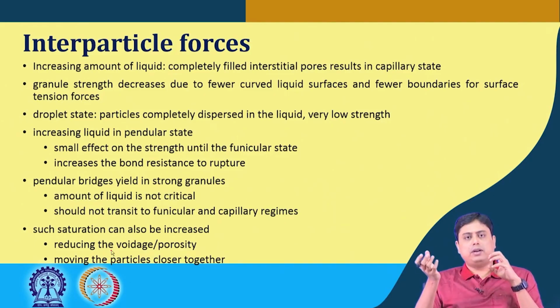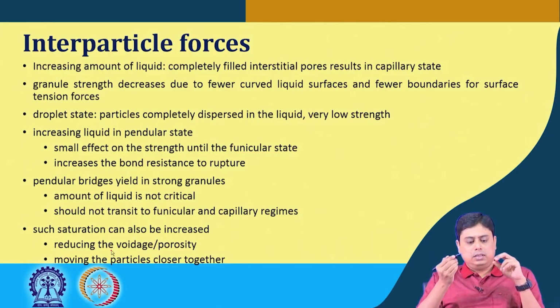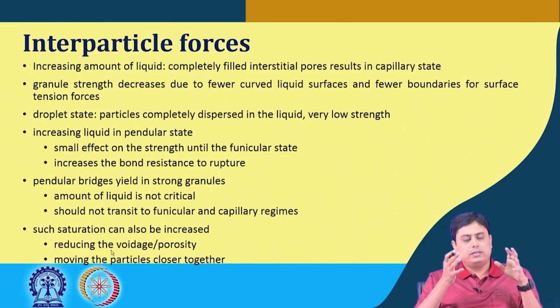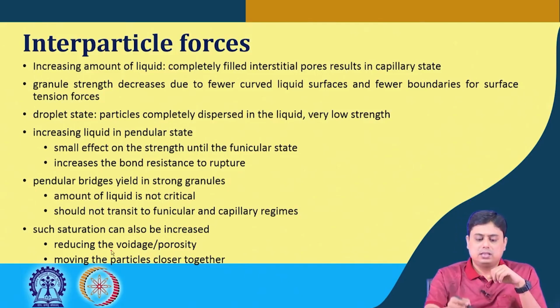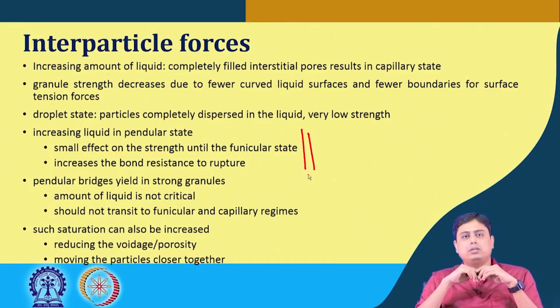But as it moves to the funicular stage, the strength decreases. So this pendular bridge yields strong granules, because the amount of liquid is not at the critical condition, provided it does not transit to the funicular or capillary region.